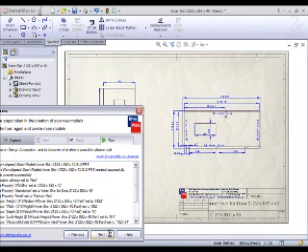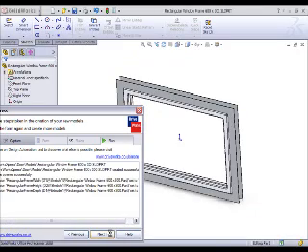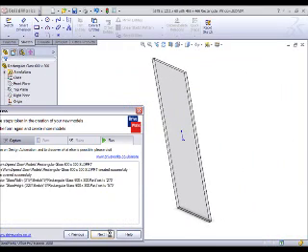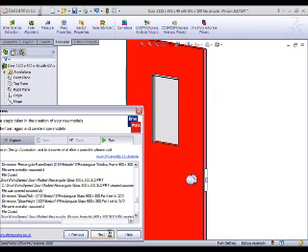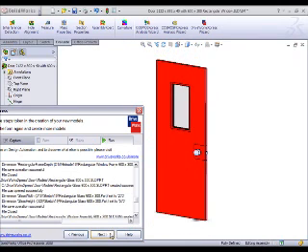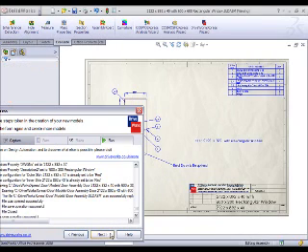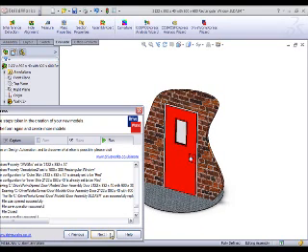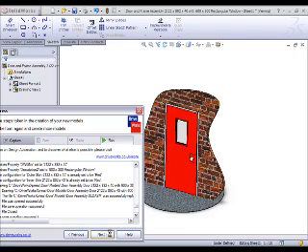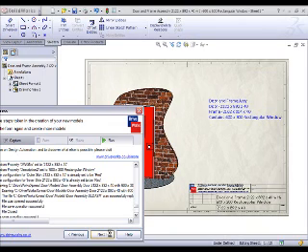It's created a new inner skin. The inner skin has also got the drawing as it had before, and it's updated the drawing border. Now it moves on to the window and the glass, which is much taller and narrower. It's done the frame again, all with unique file names. So now it puts that new window in the door, with a new drawing and bill of materials up on the top right hand side, and updated drawing borders again. It moved on to the top level assembly, moved the door into the right position, and then the general arrangement drawing of that sat inside the wall. And there we have it, that's finished.